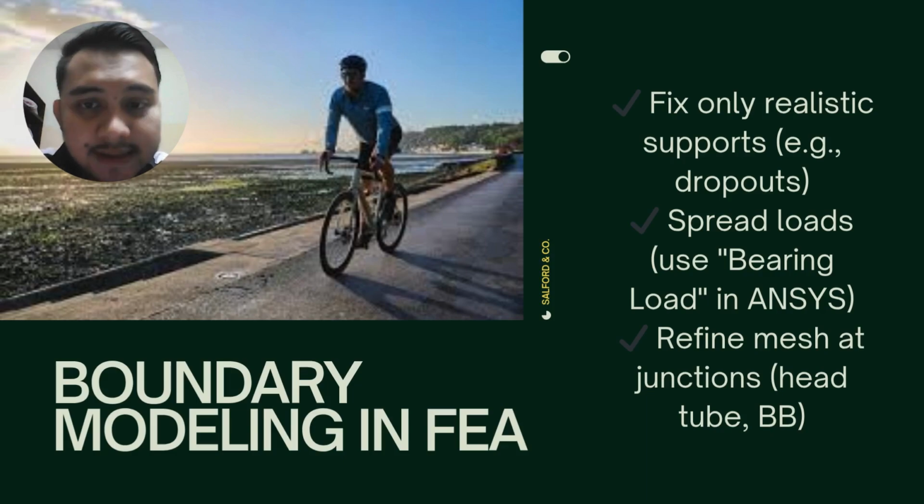And next, this slide tells about the boundary modeling in FEA. So, we fix only realistic supports, such as the dropouts. Next, we use spread loads. In ANSYS, we use the bearing load. And finally, we define the mesh at the junctions, such as at the head tube.